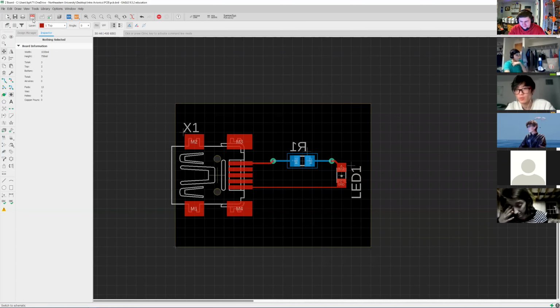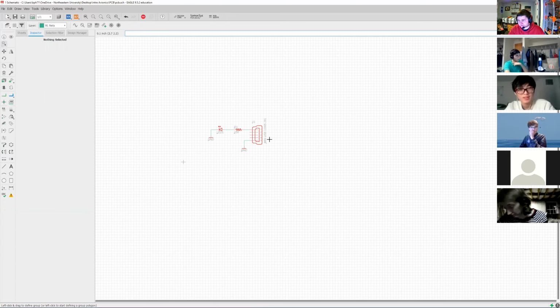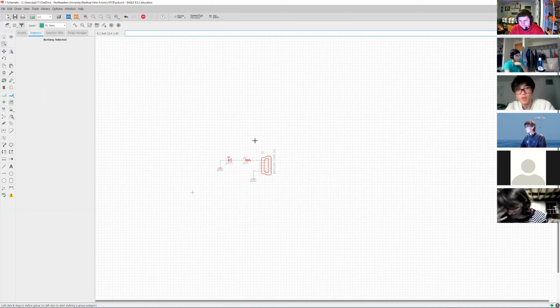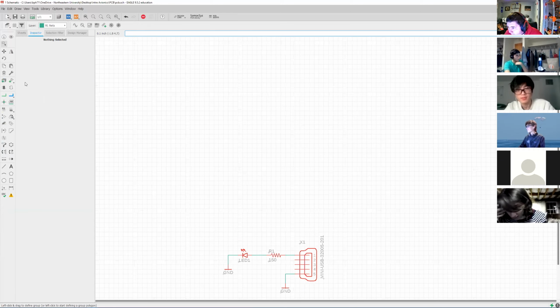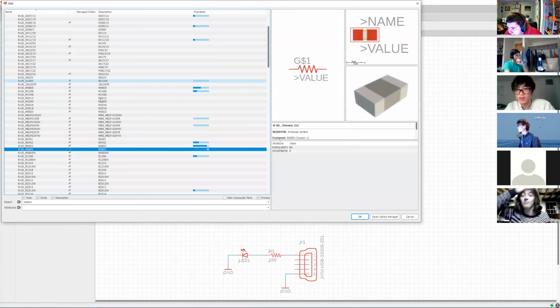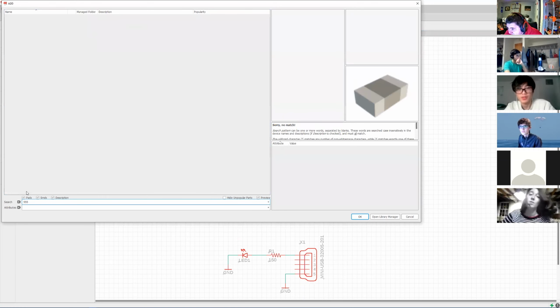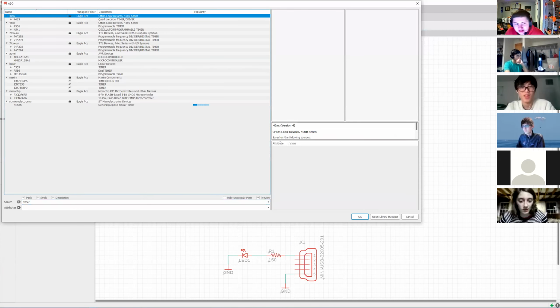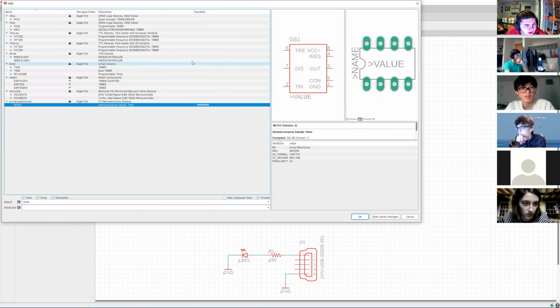So I'm just going to go back to the schematic. We'll leave this here because it's nice, we can get power for our 555 timer easily. When we go back, add part, and hope that Eagle has it. Don't type 555. If you type timer, there's a linear 555, general bipolar. Yes, here it is. ST Microelectronics, or do you want to do the linear one from Eagle PCB?